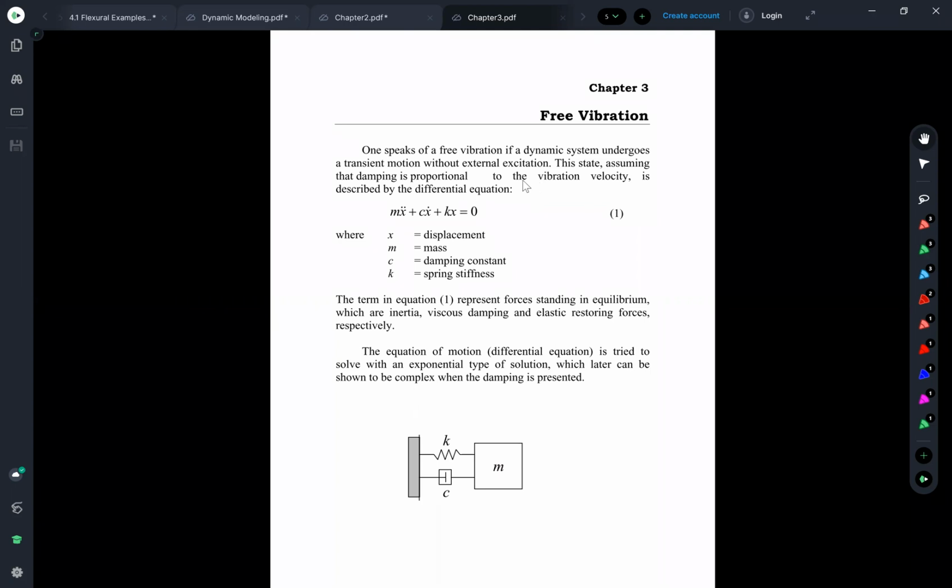If you look at the system, a single degree of freedom system, you represent your bridge or your building with only one degree of freedom. For the building, most of the time we look at the load of the structure. For the bridge, some are interested in the deflection, the movement of the midspan motion.